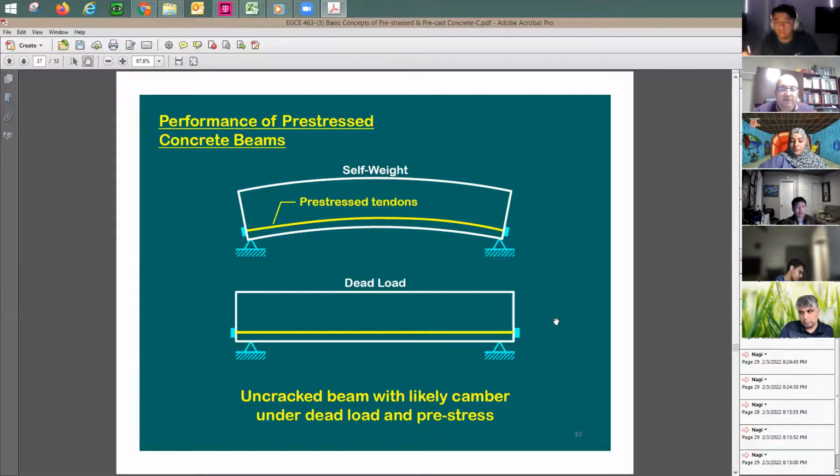The good thing about this is that in bridges, the amount of live load is almost nothing. It's very small, just negligible. But the amount of deflection due to dead load is going to be the controlling factor. So if you'd like to have a clean beam, a straight beam, no deflection, no camber, you just do your analysis and set the camber equal to the dead load deflection. And that's it. Live load is just ignored because live load is just the cars, and the weight of the cars compared to the weight of the bridge is very small.